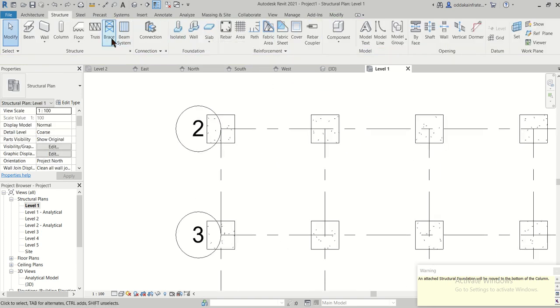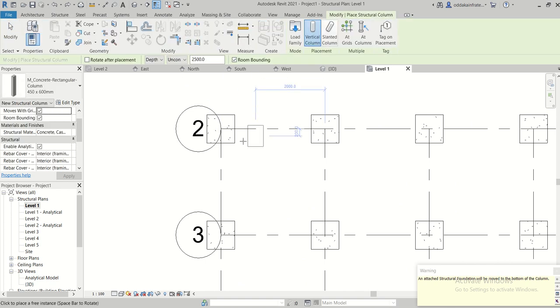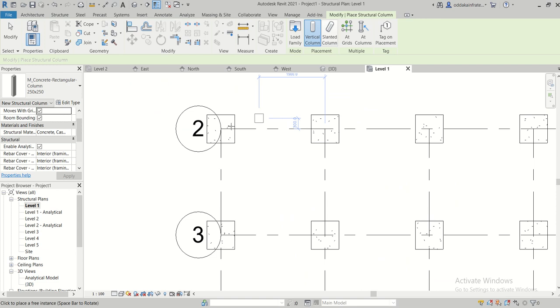To avoid that, just take the columns here, and take the particular size of the column here, and just give this option of the height here, and give this a height of, let's say, give this height and give this level 5, and then place this.